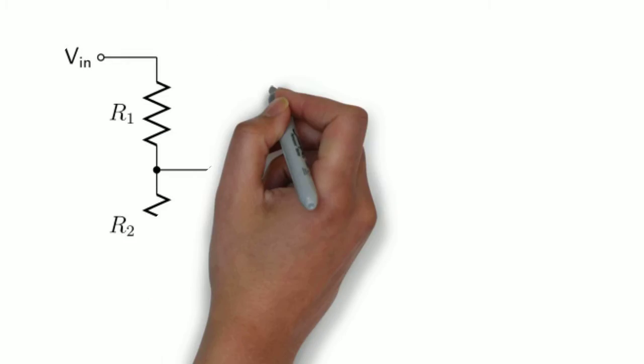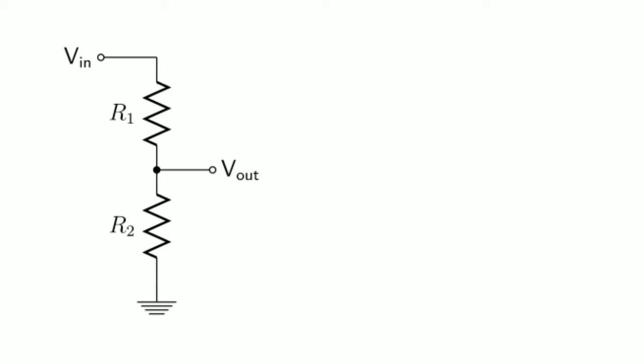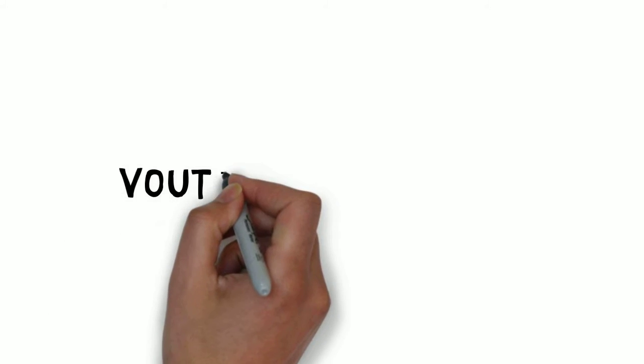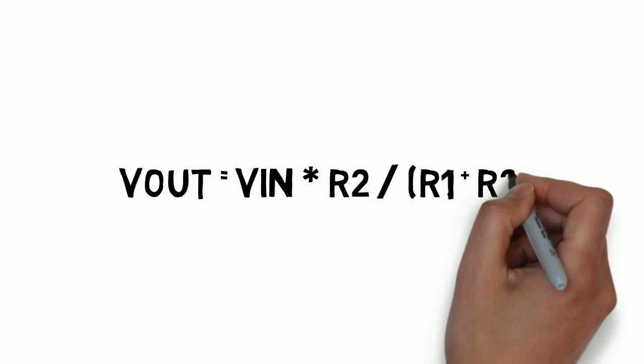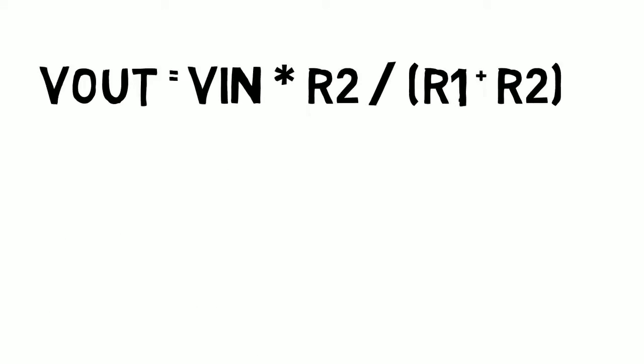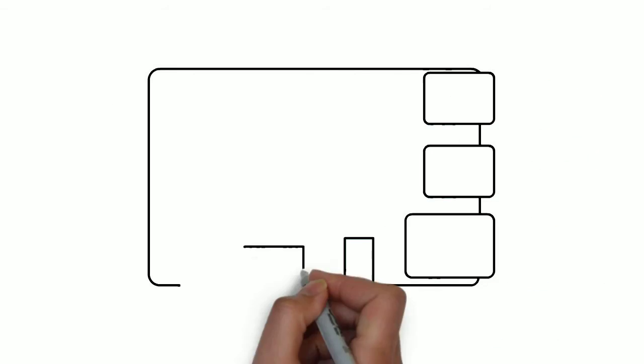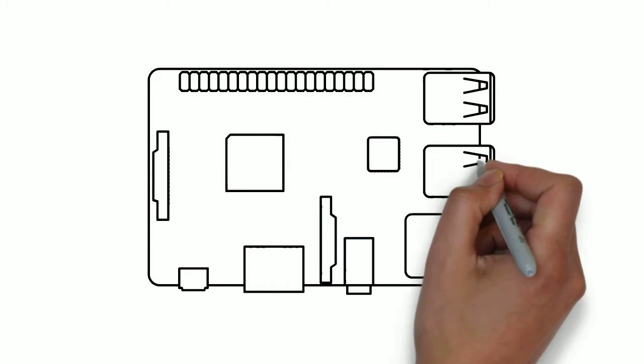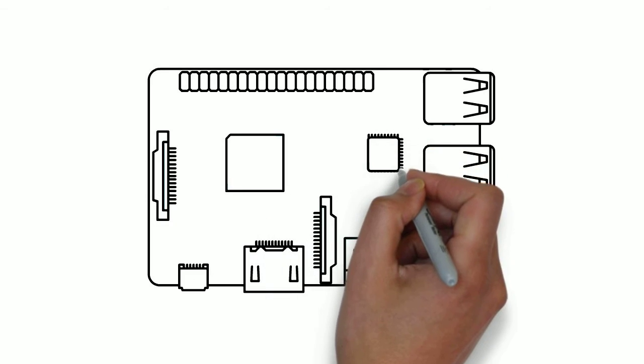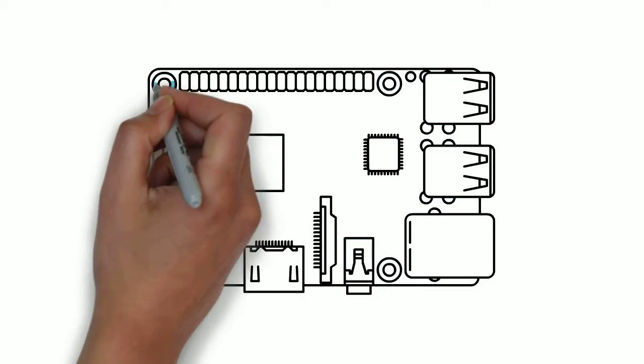Another popular use of the resistor is the voltage divider. It's the great grandfather of the linear voltage regulators that we have now. This circuit spits out a voltage at the midpoint much lower than the supply voltage. This can be explained by the following equation. Voltage dividers are used as logic shifters or level translators in digital circuits to step down voltage from one level to another level between these digital components.